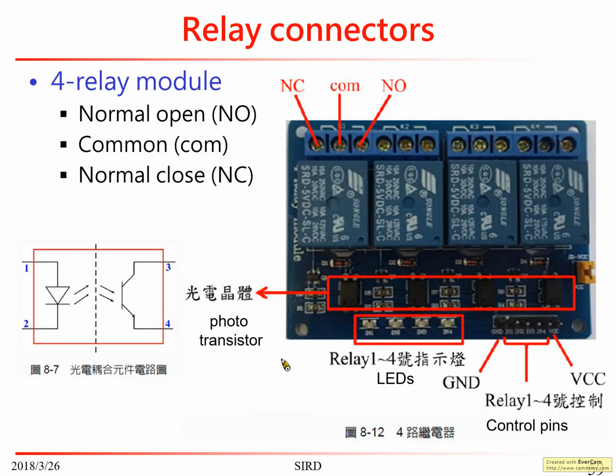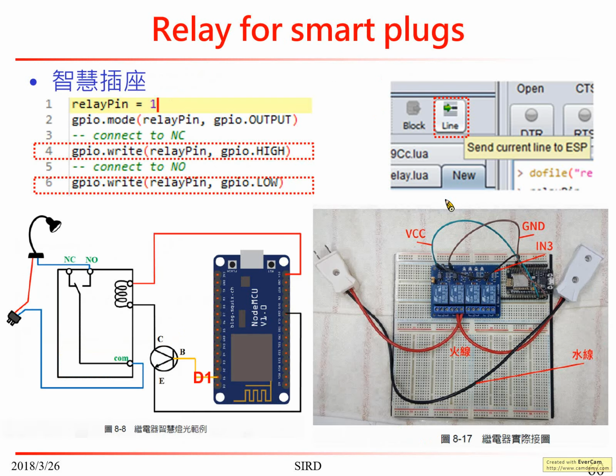So anyhow, you can just think that suppose right now we have a 4 relay here, right? And this controls the first one, okay? If I apply 1 here, then these two will be connected, and these two will be disconnected. If I apply 0, then these two will be connected, but not these 2 points. Similarly for the rest of the relays, they operate in the same manner.